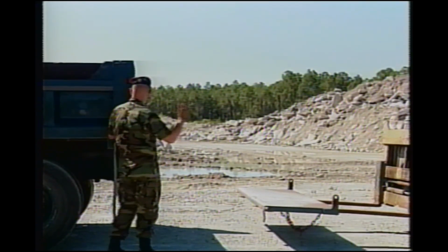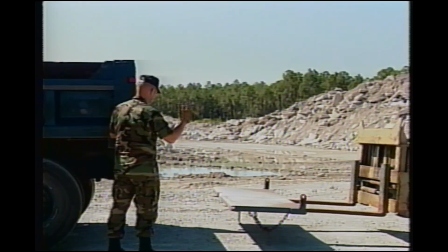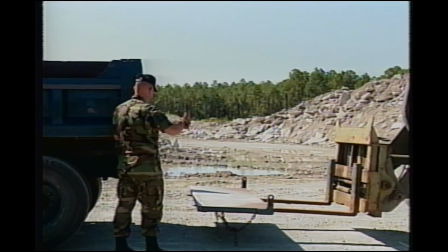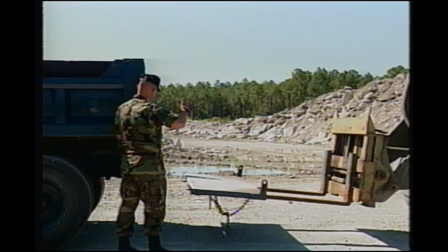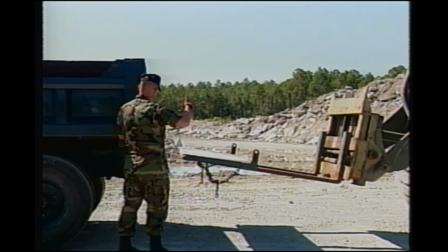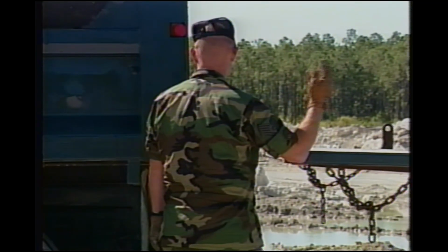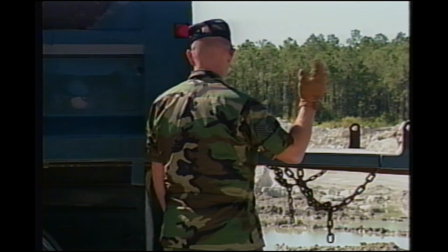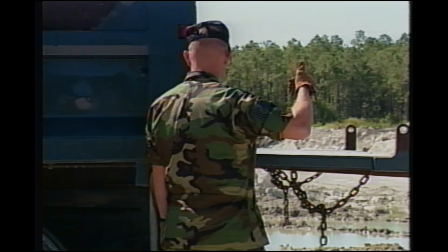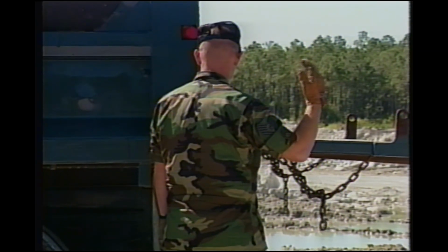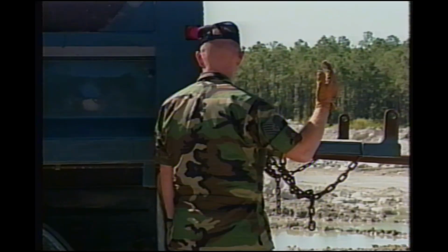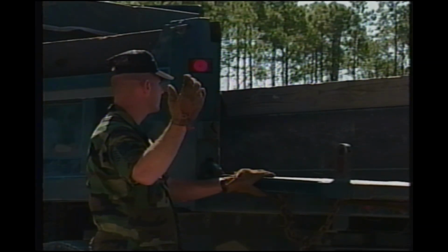Position the forklift so the tailgate is aligned with the bed sides. Raise the tailgate until it is even with the bed floor. You might need to adjust the tailgate a little to get it to align properly. The final alignment process must be a coordinated effort between the guide person and the forklift operator. Hand signals are critical here.